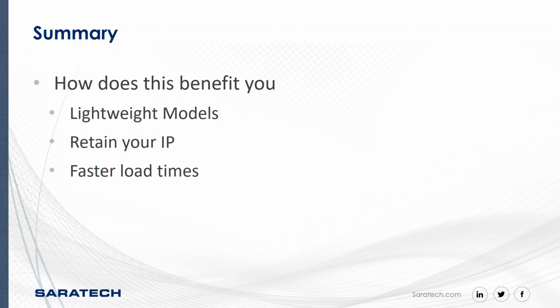So again, it goes back to what your real design intent is. If you're taking a large component and you just need to have it somewhere to make sure you have the space or make sure there's no other interferences, definitely do the top level assembly. If you're just trying to enhance performance, then focus on the features that maybe you have a lot of those components inside your assembly, or they're very complex components, and utilize this tool to simplify those.